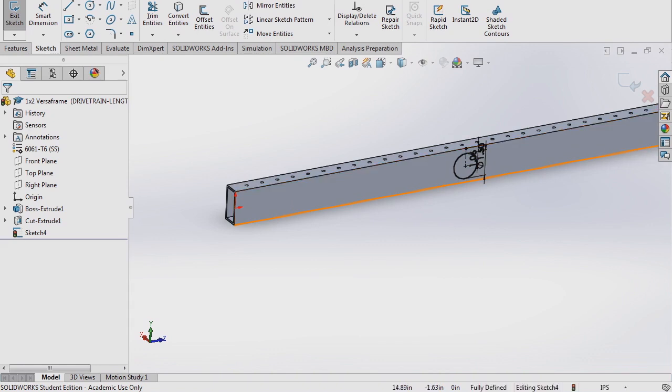So this can either be belts and pulleys or sprocket and chain. For drivetrain, it should be chain or 15 millimeter pulleys, which is the thicker pulleys, and belts. But for our situation, we're going to be using chain just because it works with the gearbox we want to be using. So we hook up the chain from the middle where the gearboxes are to the outer wheel in the front, and then another link of chain from the center to the outer wheels in the back.